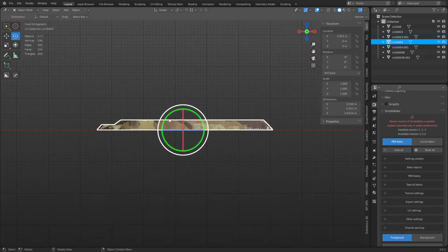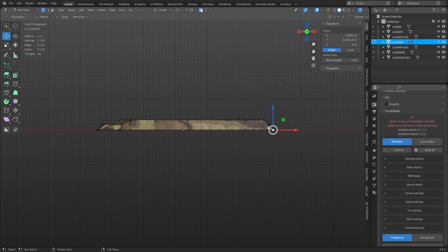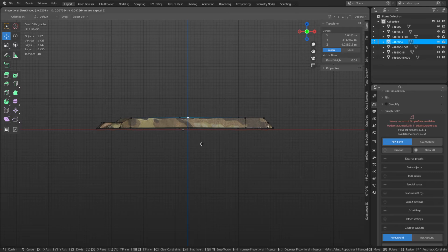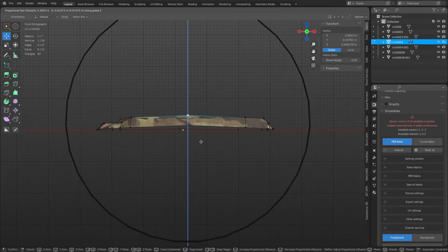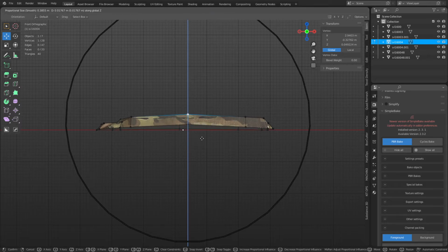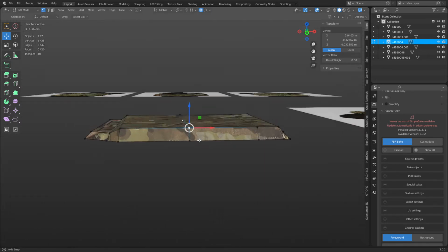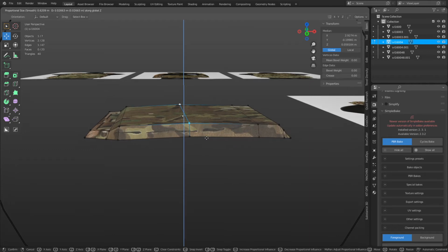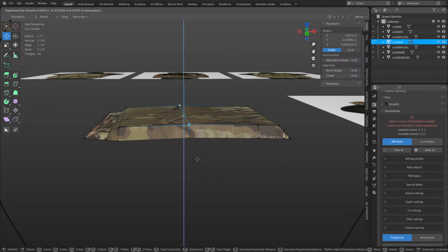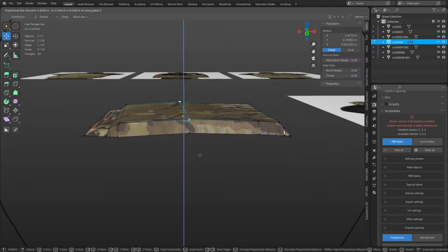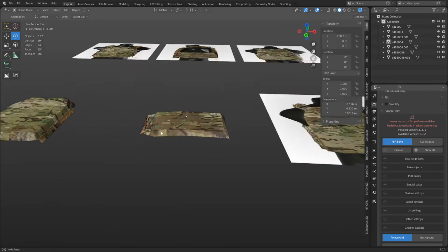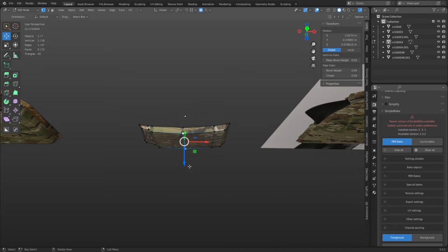And then this should be curved all the way around, so we're going to use proportional edit. I'm just going to grab the center. Should have a slight curve to it, I think. So proportional edit, once you turn it on, which is that little icon there, you can use smooth or different fall-offs. Use your mouse wheel to change the size here. You do that number. So I'm going to go all the way across, and you can see I have correct face attributes on. Turn that off. You know, don't get carried away with that thing. Probably has a slight curve to it, I'm imagining. Maybe even more than that.